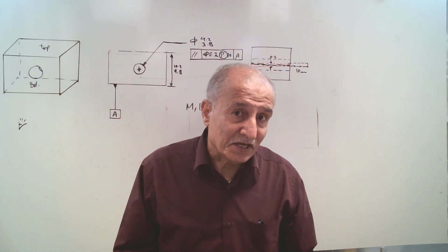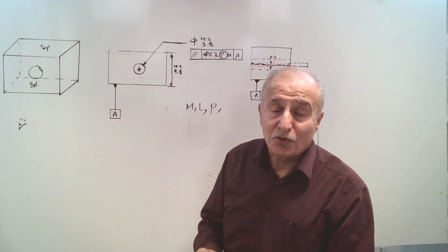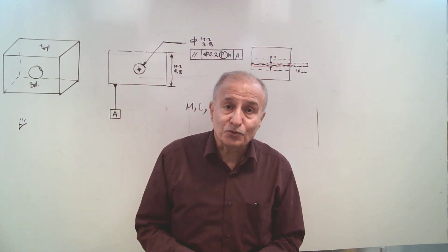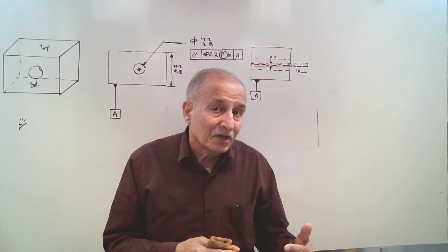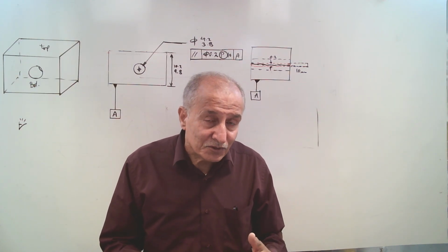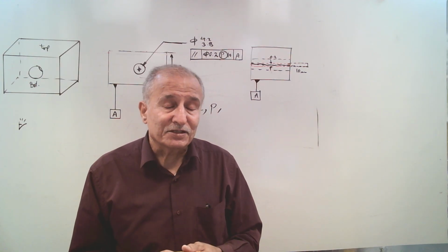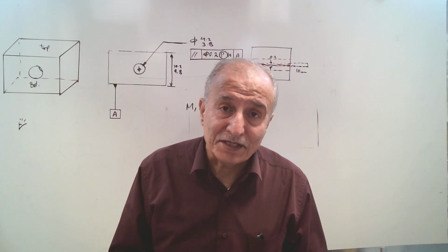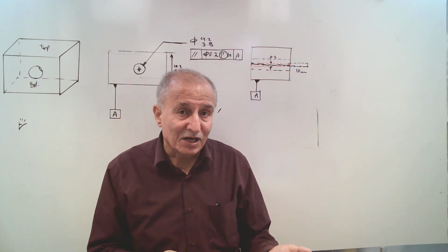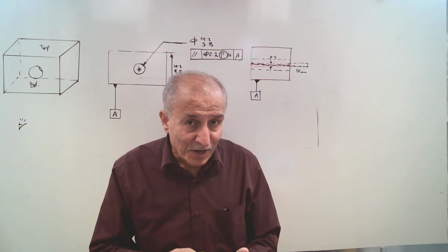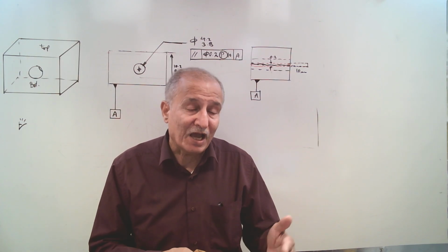Tolerance at MMC size is exactly this amount that is mentioned here in the feature control frame. And also bonus tolerance is permitted. And the zone shape is the same narrow cylinder for the axis. And zone size is variable because you have an M or L modifier: at MMC we have 0.2, or with the L modifier at LMC we have 0.2.